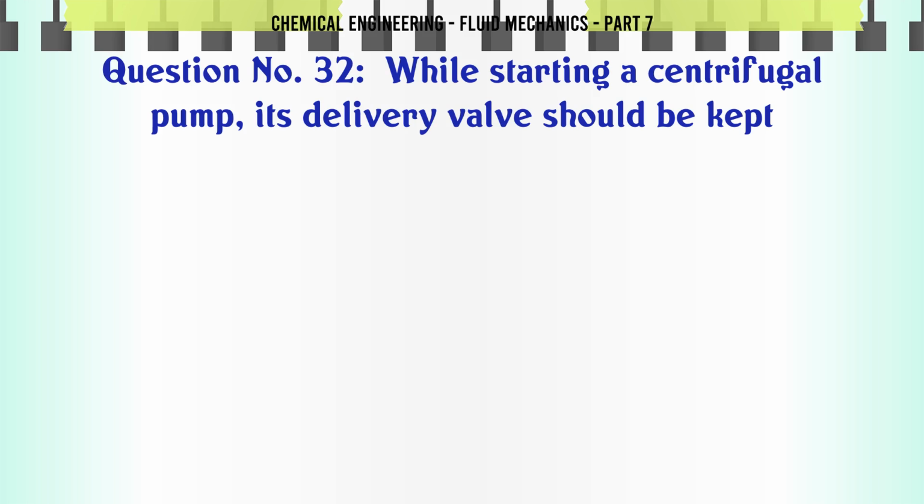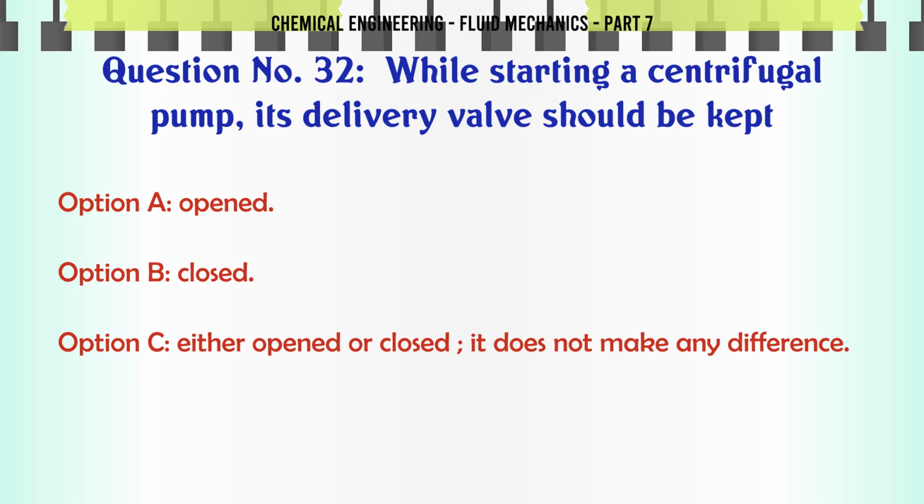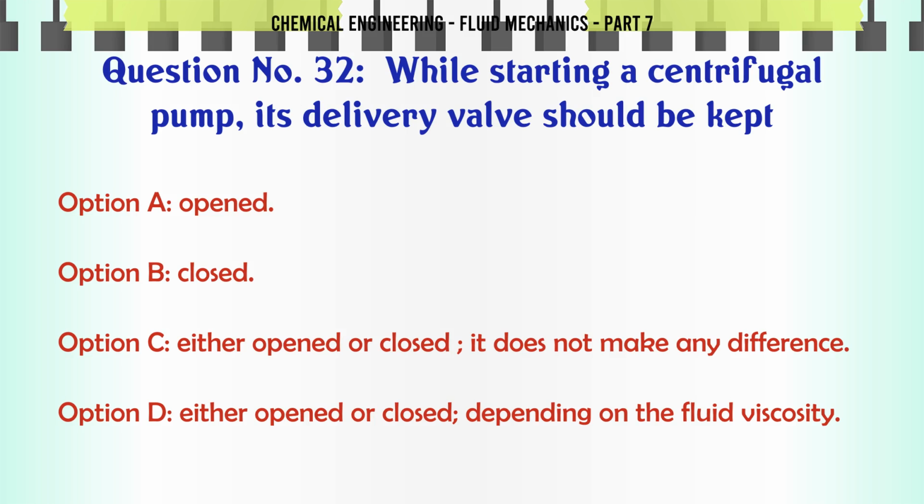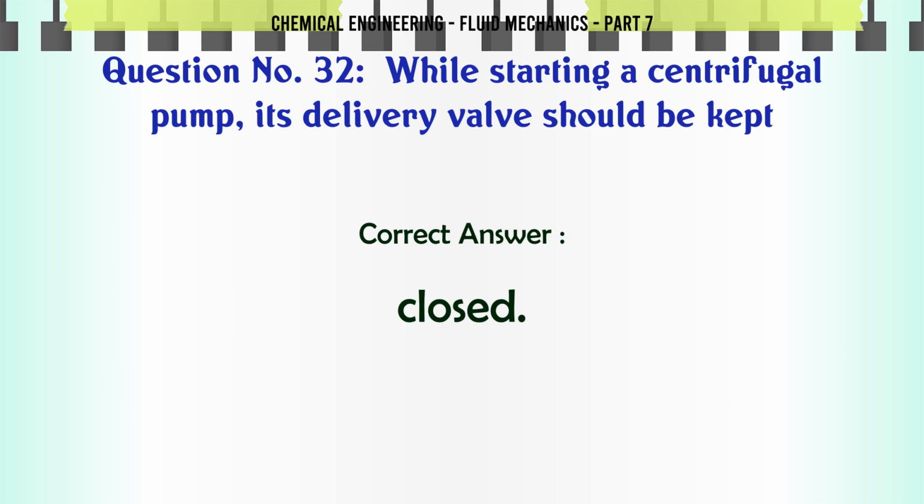While starting a centrifugal pump, its delivery valve should be kept A opened, B closed, C either opened or closed, it does not make any difference, D either opened or closed depending on the fluid viscosity. The correct answer is closed.